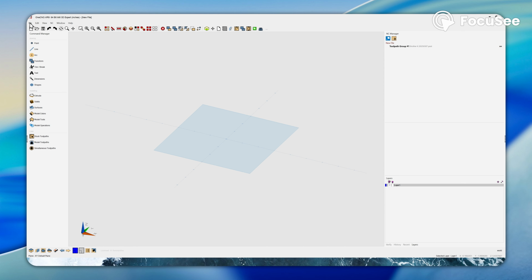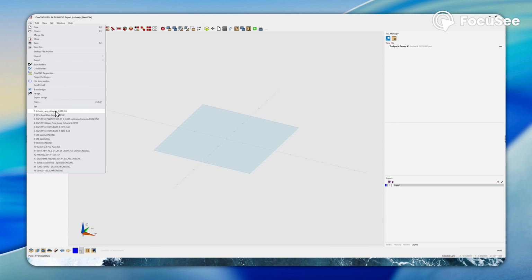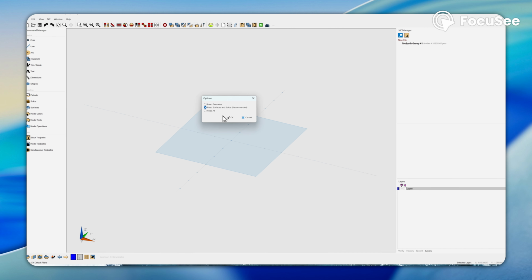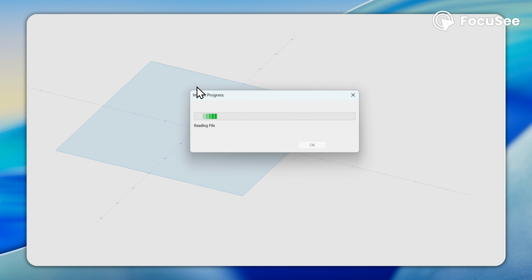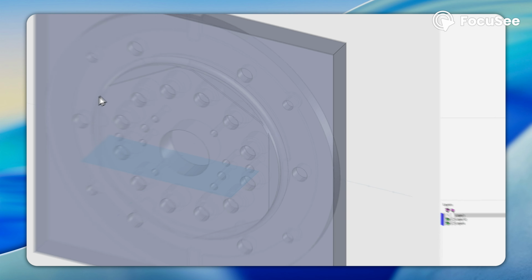So this is pretty simple. Usually, what I do is I take SolidWorks and I create an assembly of my part in the stock, and sometimes I'll throw my vices in there as well, and then I export that assembly as an IGES file, and I already did that somewhere else. So what I'm going to do is import the IGES file. It's already here, so I'm just going to open it and pick the recommended. Here we go, and I say OK, and then this is the assembly.